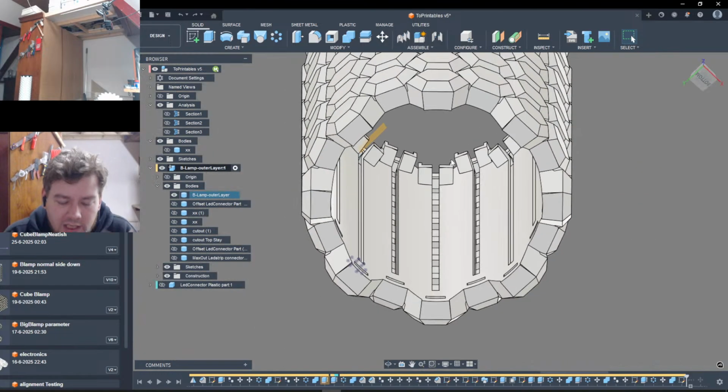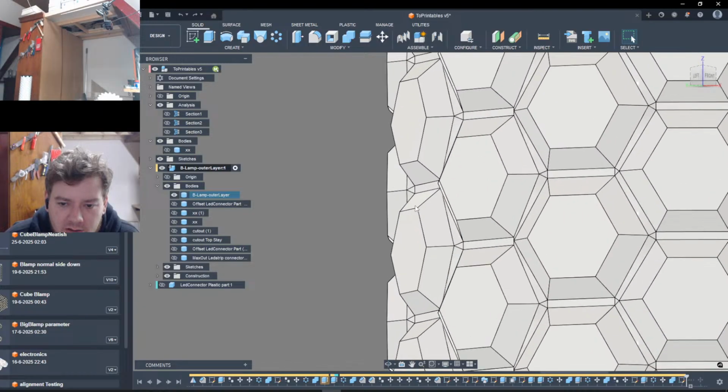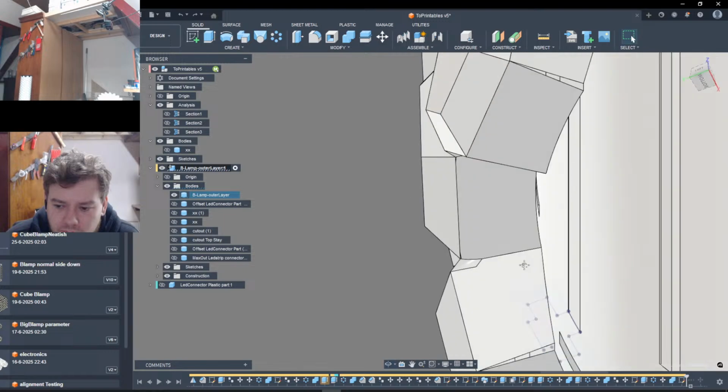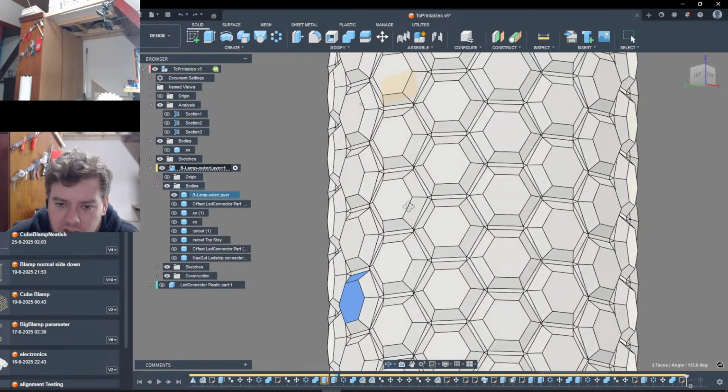Because I keep in mind that I can push to 40, but I always do 45-degree angles, and if really needed, I go to 40 because I know printers can do it right now. But I'm always watching, so I kept the whole design of why this angle and this angle is also in 35 degrees, and that works.